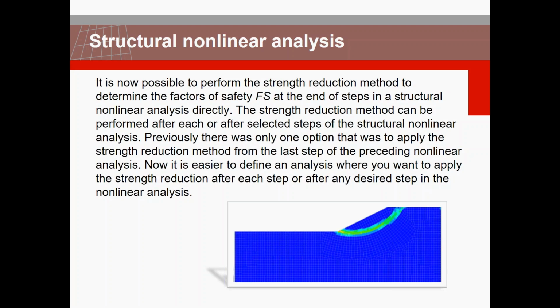Further on, for structural nonlinear analysis in combination with the strength reduction method, as I mentioned, most of the clients now do this type of check to consider the stability of the overall model, while part of the site goes for construction, or maybe there is an earthquake and they want to see if the model remains stable when the earthquake is happening. Therefore, now you can combine your strength reduction method and structural nonlinear analysis sequentially or after several steps. So it's up to you, and you can assess and evaluate the factor of safety of your model at any stage of your analysis.